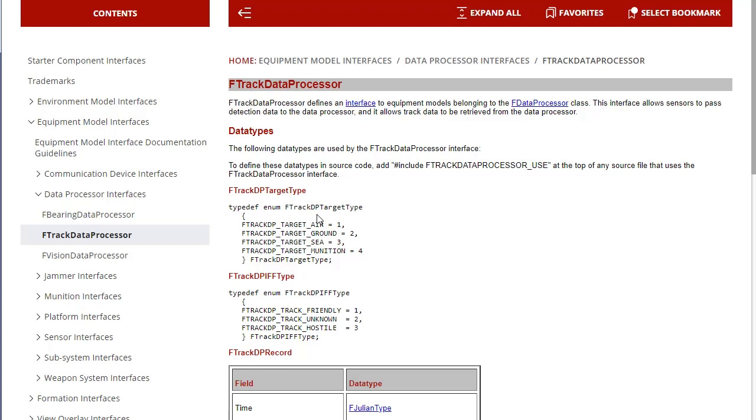Even if you don't document it, it is important to check interfaces. You may define your own interface names, and so only your models use your interfaces, and you don't care about anybody else using them. But you still want to check the interfaces because you don't know if a user is going to take your model and try to attach it to a unit with other models that you didn't develop, and the models aren't going to work together. So you need to always set interface tags and check your interface tags whenever you have models that are interacting with each other, if for no other reason, just to make sure that nobody tries to use your models with other models that are not compatible. So if that's all you want to do, you just have to put a couple of character strings in a few places and you're good to go.